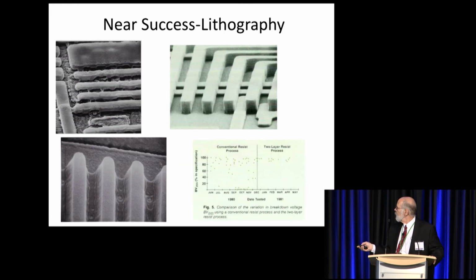Okay. So we had a near success. We had a lithography program. We eventually got a GCA aligner, an optical aligner. It was pretty good. It gave line definition that looked like this. But we could not make these circuits work, try as we might, because there is just a little bit of metal left even after we over-etch these circuits. You can see down a picture now of that same optical path looking down. You can see a little webbing of standing wave problems that cause lack of the resist to bleach out.